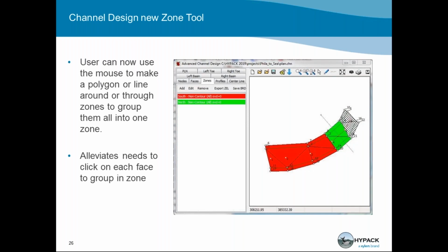This is what you'll see on the DQM computer aboard the dredge. Usually it's a standalone computer, and it runs this software exclusively. So to make sure that all the data is being received from HYPACK, you'll go over to this PC, and through the serial, the network interface, you'll make sure that it's being populated with all the pertinent information. It'll also show you at the very bottom when the last bit of information was sent out to the Corps. It's hard to have a good internet connection out on the dredge, so you want to try to monitor this to make sure they get all the information they want.